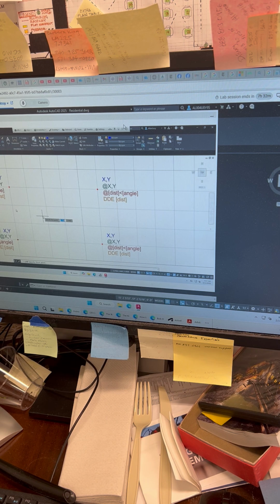And that coordinate is 1, comma, and you can see as soon as I enter the comma, oh, I thought it was going to do it. You can see how it's entering that information at my heads up display. So 1, comma, 1, there we go. 1, comma, 1, and as soon as I hit enter, my line starts from that absolute coordinate.